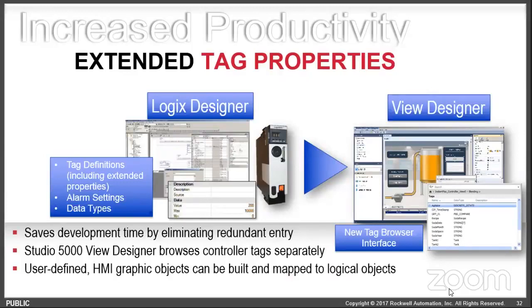Is anybody here using that metadata for the extended tag properties yet? We got one. So the ability got added in with the newer versions of Studio 5000, where now you can add, let's say, engineering units and different pieces of information, but instead of adding it to your instruction logic or the actual code that you're running, so let's say you have a 3 meg controller, it doesn't use up that memory, it actually goes on non-volatile.